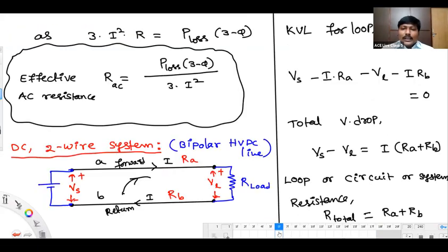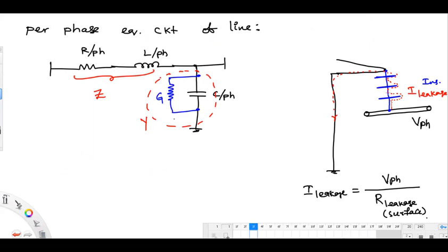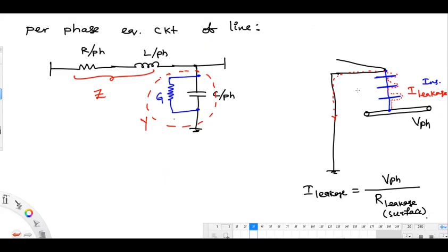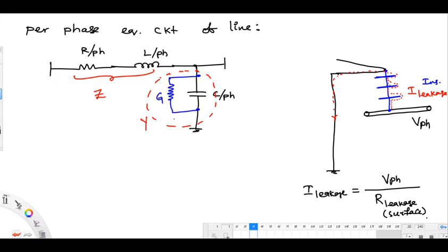See, actually, you are applying some voltage across the insulator. After all, it's an insulator. You are applying some voltage, meaning voltage by that impedance, so definitely some amount of current should flow. But this insulator body resistivity will be very, very large in number. But surface resistivity is very low.